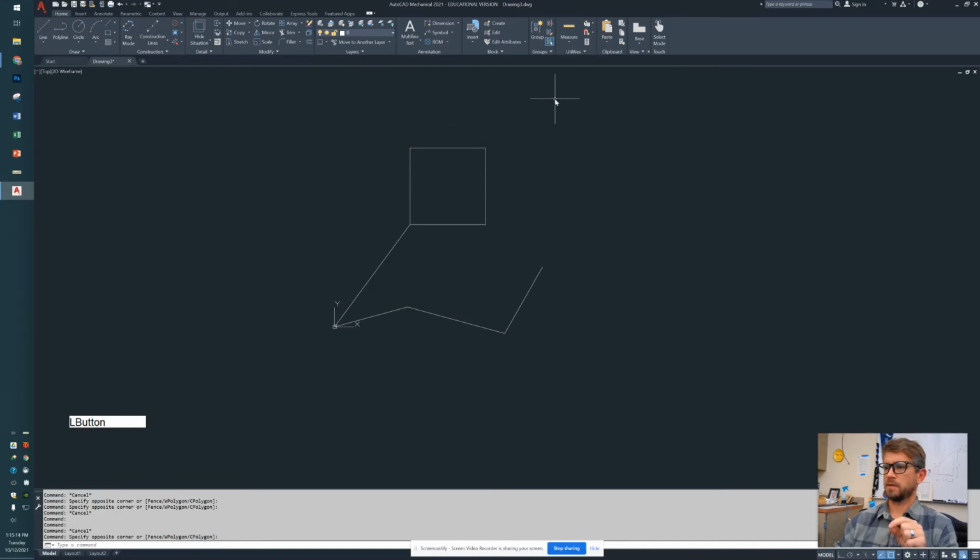Okay. Notice if I click from the right and move the box, it is green and dashed. And as soon as it touches, it'll select it. Okay. So depending on what you're trying to select, maybe a blue box is better, or maybe a green box. Push escape to deselect. You can also click and hold, okay? And this is just gonna select what's inside of the box, but I can draw a shape. Same thing coming from the left side, okay? Anytime I touch it, it's going to make a new selection anytime that line gets on there. So escape.